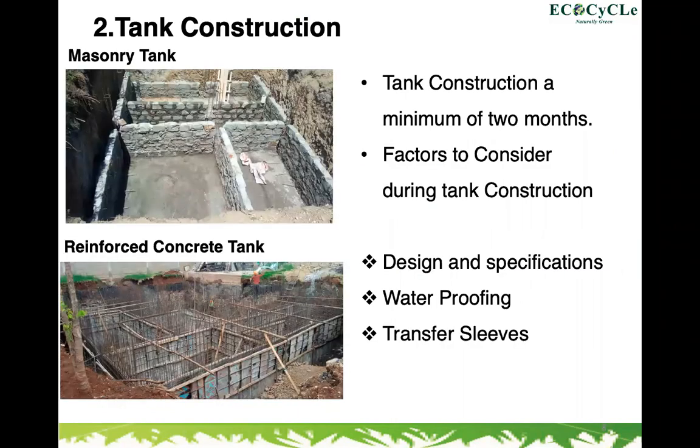Next, yes. So the tank construction, we have different factors that have to be considered. The end use of the top slab. So if maybe someone wants to use it as a parking area, then the tank that we recommend is usually a reinforced concrete tank. But when maybe it's used as a laundry area or just as a hanging area where we have no load that will be applied on top of the tank, then a masonry tank would do.